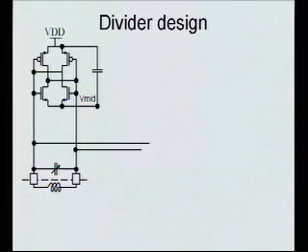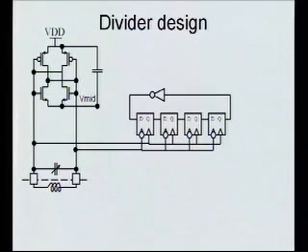So here's our oscillator again. I've stretched it out a bit. And I feed it into this, my divider. I always called this a ring divider until last year's ISSCC when someone else put it up there and called it a Johnson counter. So now I know it has a name. Before that, I never knew. The basic way this works, I'll show some simulations in a moment, is that every cycle of the oscillator, one of these D flip-flops takes its input and transfers it to its output.